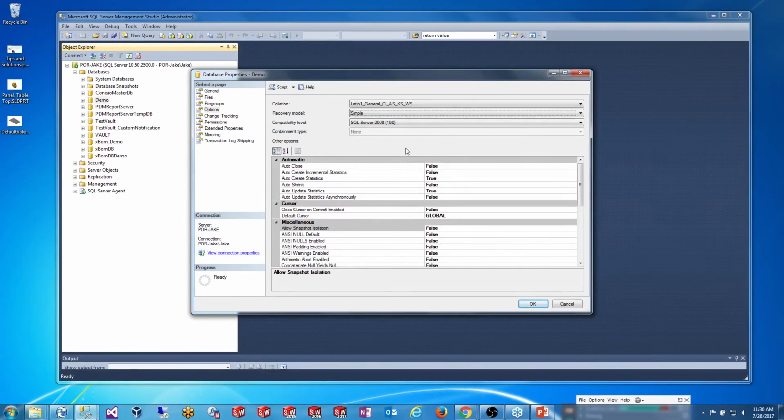as it starts to grow, those of you maybe on the IT side would know that if you have any kind of auto growth enabled on your hard drive, if your hard drive is set to increase its size as needed, that can cause fragmentation of your transaction log, which is a big performance hit for PDM, and I've seen it cause a lot of issues with any kind of database activity. Anytime the PDM system needs to access the database, that could potentially be very sluggish.